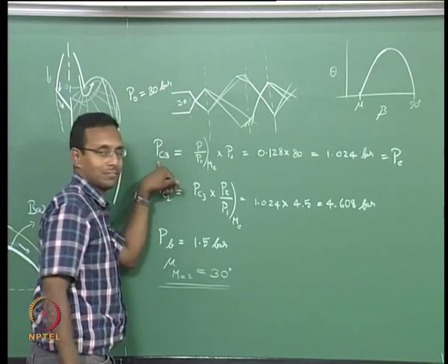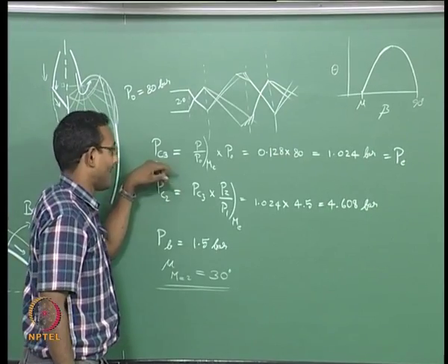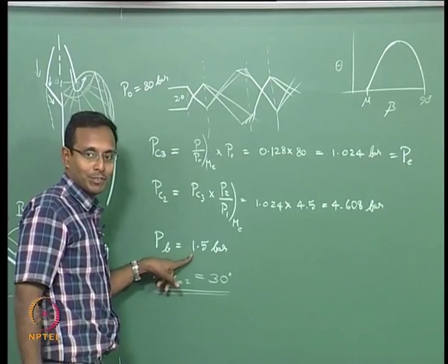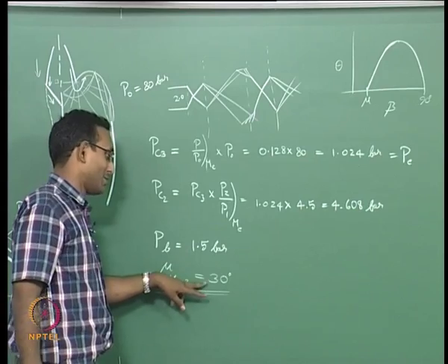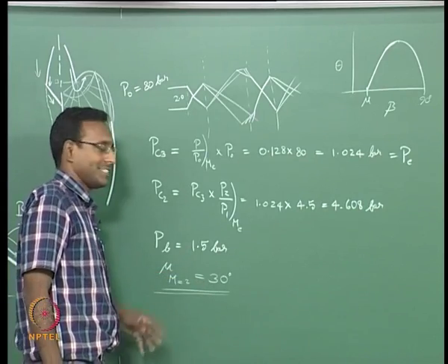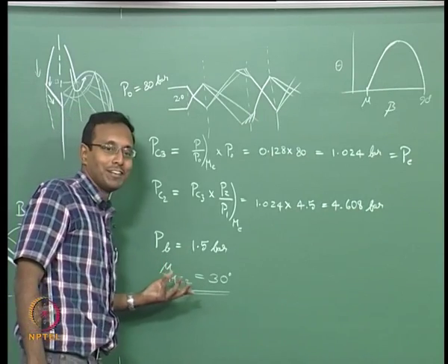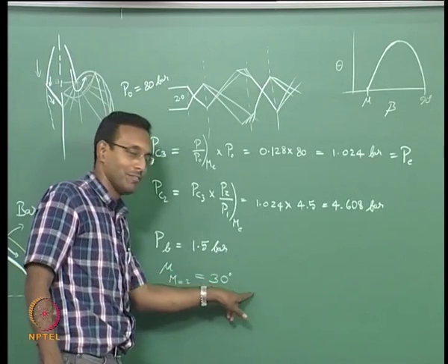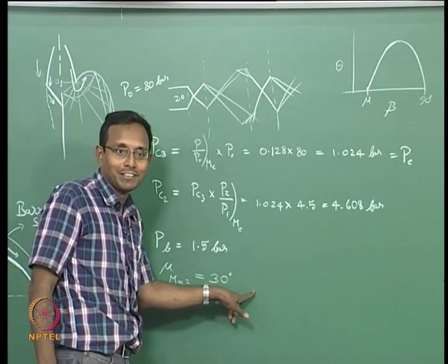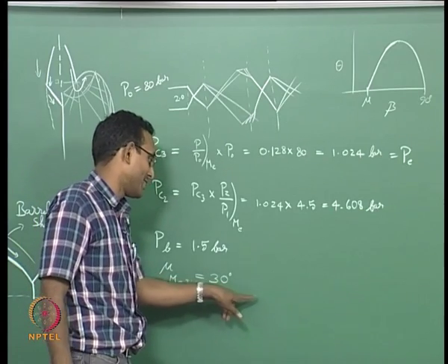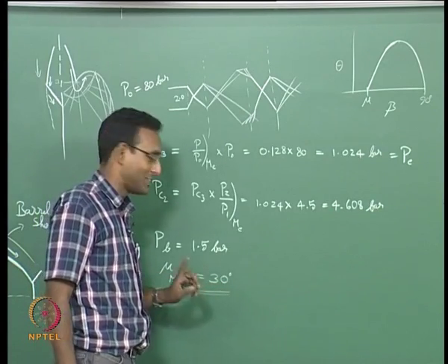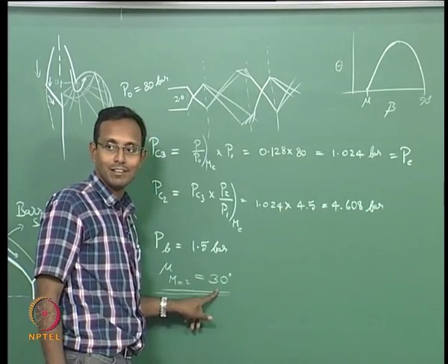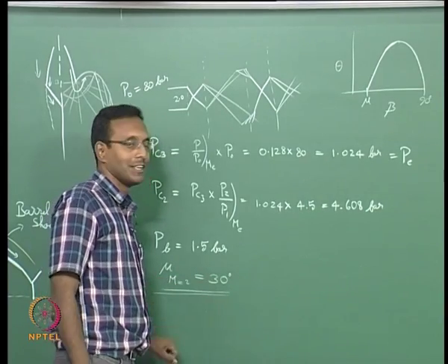That's my P critical 3. While I chose 1.5 bar as my back pressure. So I want to choose something close. Let us say I will choose 40 degrees, 50 degrees, that kind of number. Start from there, and I know the answer should be somewhere between say 50 degrees and 30 degrees. We want to work through that with iteration and get to the answer. I know the answer is definitely more than 30 degrees.